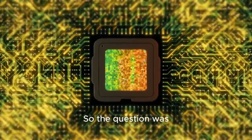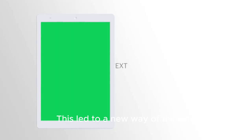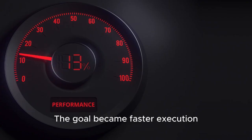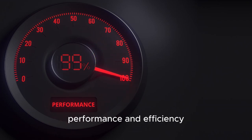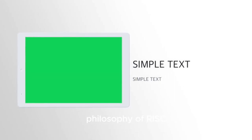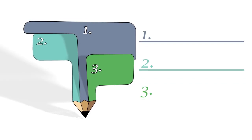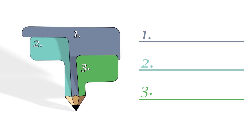So the question was, why build these incredibly complex and expensive processors if we're not even using most of their features? This led to a new way of thinking. Let's simplify everything. The goal became faster execution, simpler hardware, and better overall performance and efficiency. This brings us to the design philosophy of RISC, which can be summed up in one word: simplicity. The core principle is that a simpler instruction set allows for a simpler and faster processor.